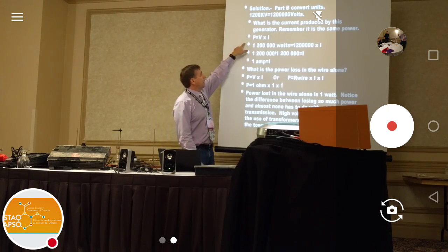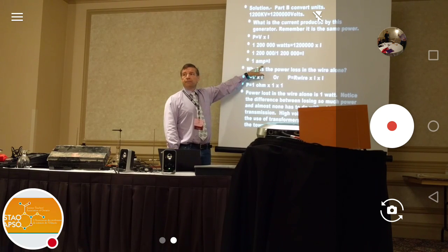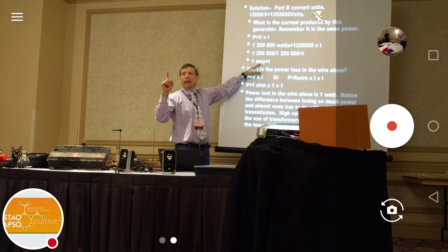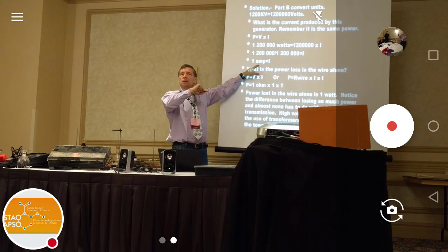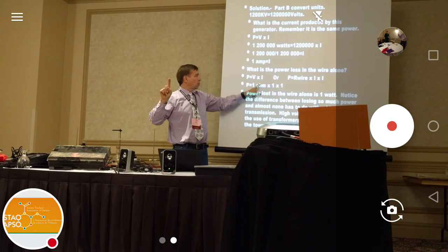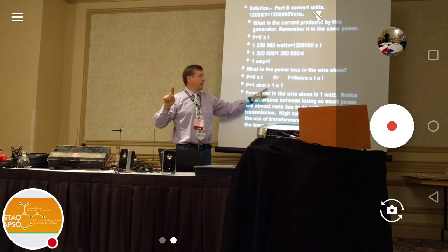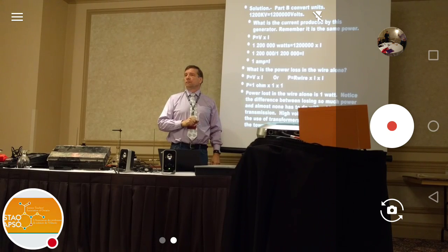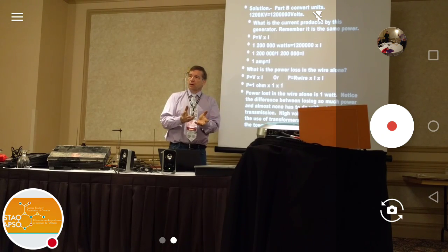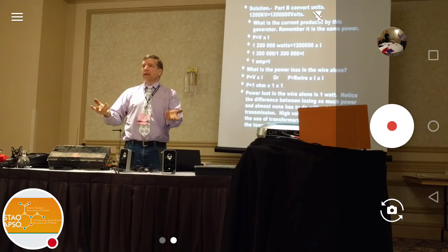And then there's my power. There's my voltage, what current, I'm getting 1 amp now. Wait a minute, 1 amp? That power is going to the town, it's got to go through that 1 ohm. 1 ohm times 1 amp times 1 amp, I'm losing only 1 watt. That's why we use alternating current to generate electricity.